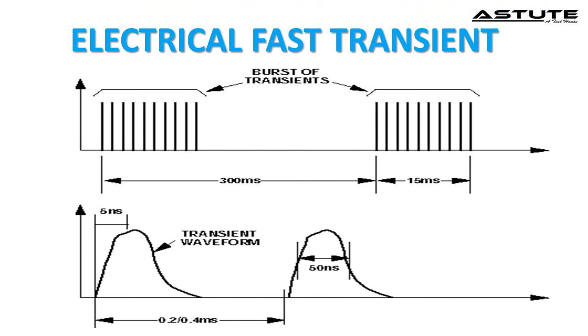Inductive loads such as relays, switch contactors, or heavy-duty motors, when de-energized, produce bursts of narrow high-frequency transients on the power distribution system. These fast transients can also be produced when the utility provider switches in or out the power factor correction equipment. That transient voltage has an effect on the equipment. So in this test we can test the immunity of equipment to the transient voltage.